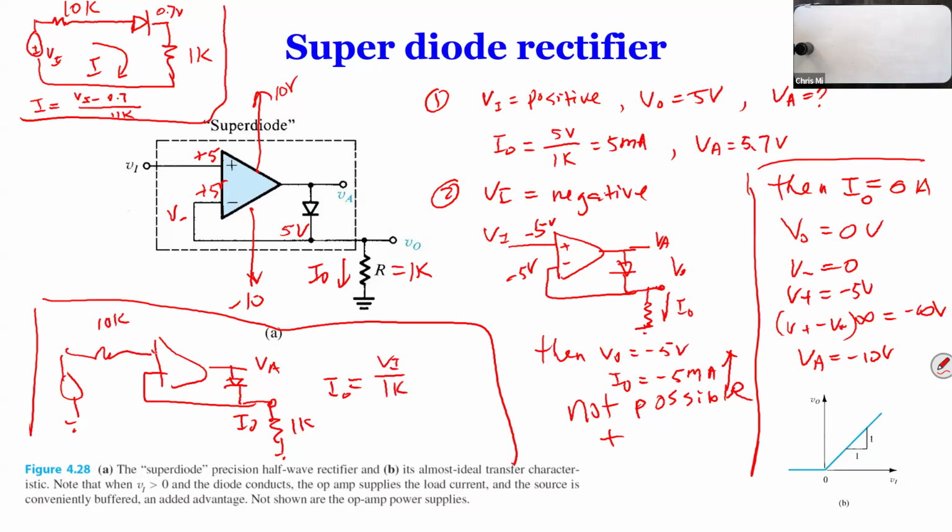The reason is VI, because there's no current into the input terminal. The voltage at the input is connected at the gate, right? So if this is VI, and this VI, and this VI, then VI over 1K gives you the load current. But on the top one, you first subtract 0.7, and second you divide by the total resistance of the loop. That's why you get much smaller.